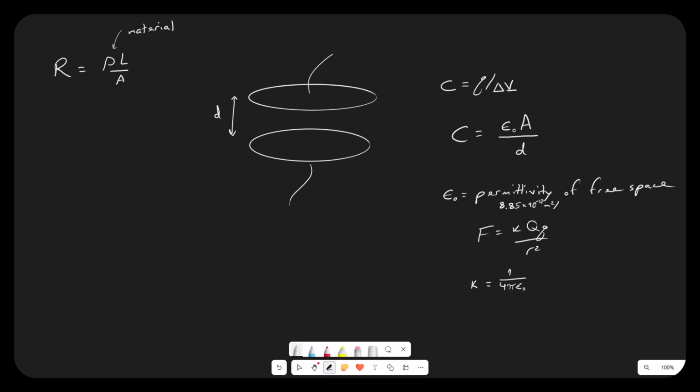meters squared per Newton Coulomb squared, which is kind of a strange one, but we can also say that is farads per meter. Capacitance has units of farads, which get a capital letter F. A farad is a huge capacitance. We generally deal with numbers in the nanofarad range or even picofarad range. Sometimes we'll get into microfarads, but we're talking really big capacitance values at that point.